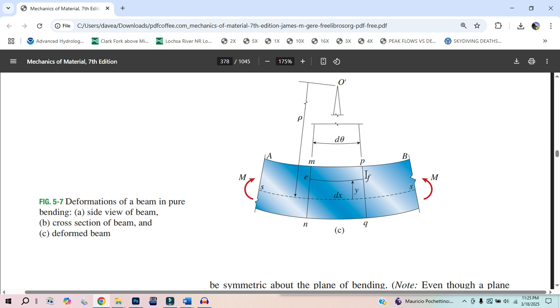When we apply this moment, the derivation is more just from visually what we see. It's from the strains that we see. That's the place to start. I visually see that this crunches and this stretches, and the only way for that to happen is if there's an axial force crunching these two sides together. From M to P, there's a force going this way in the negative direction and a force going this way in the positive direction, and that's crunching.